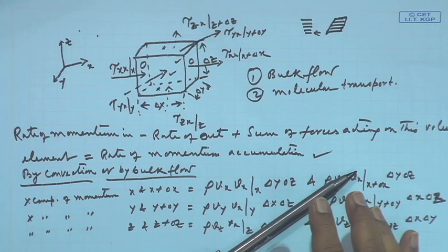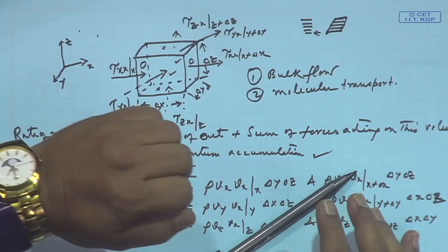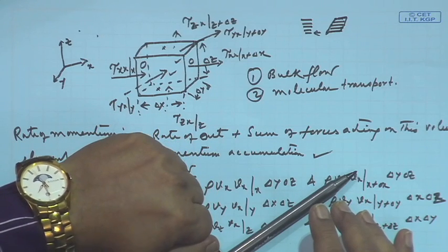So, a fluid was flowing. The moment it has a velocity v, it will have three components, one acting in the x direction, one acting in the y direction, and another acting in the z direction. So, all these three directions we have taken care of due to the velocity component Vx, that is how much momentum is being transported to all three directions, x, y and z, that we have taken care of, right. So, both at the inlet and also at the outlet.